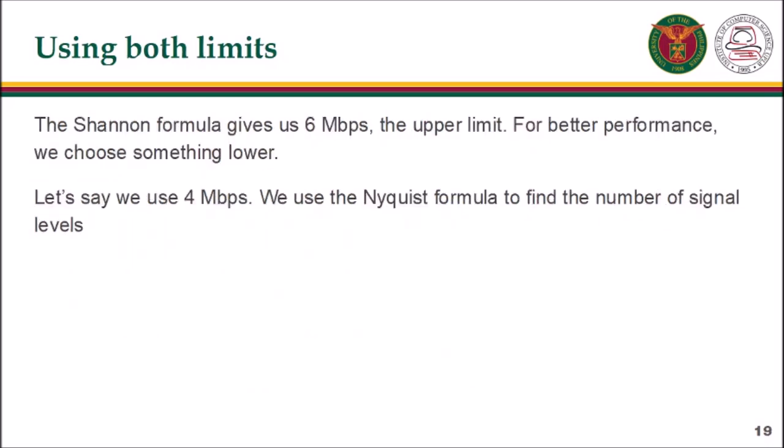Shannon formula gives us 6 megabits per second, the upper limit. For better performance, we choose something lower. Let's say we use 4 megabits per second. We use the Nyquist formula to find the number of signal levels.